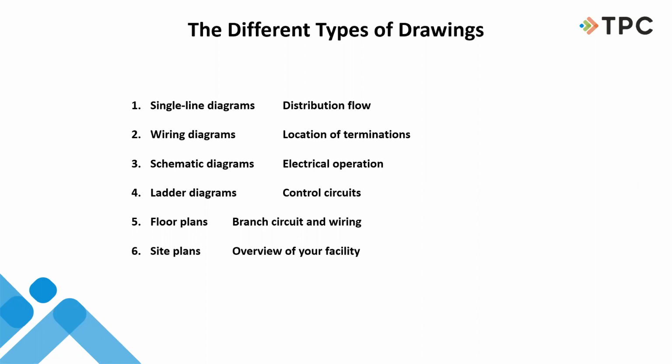Sometimes they end up in somebody's locker or something, I guess, but we don't have them. So wiring diagrams can help us know where things are. Schematic drawings, back to that information on the controls and relays and all the things that are in the box, can really show us what set of contacts it goes through and those kinds of things.